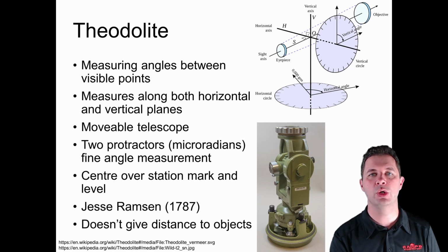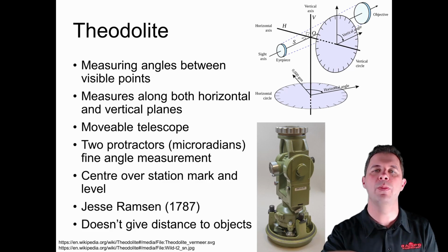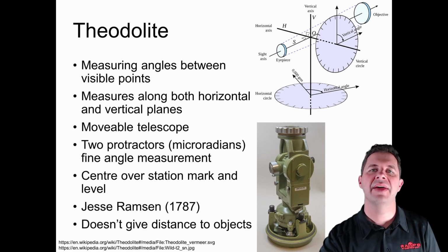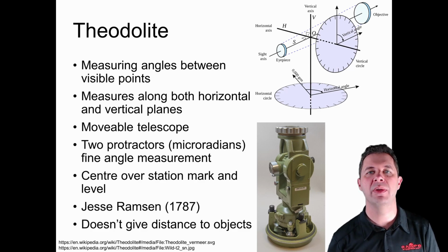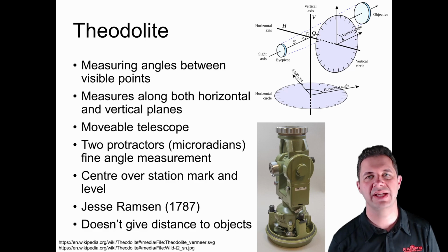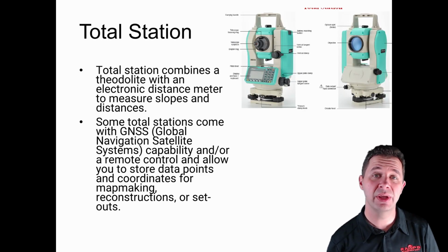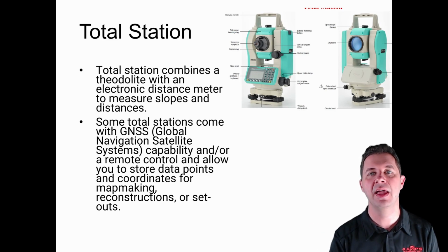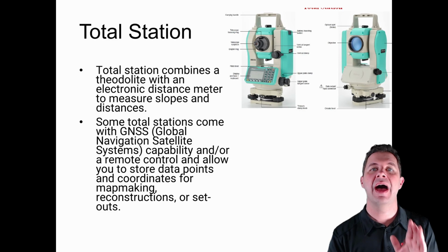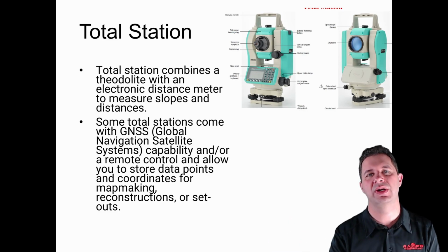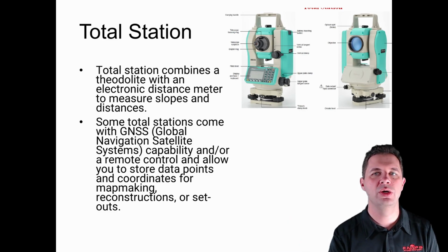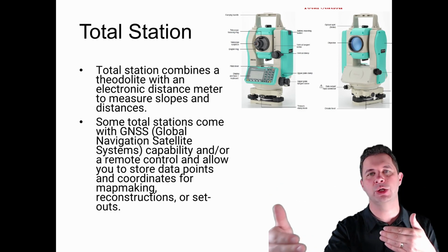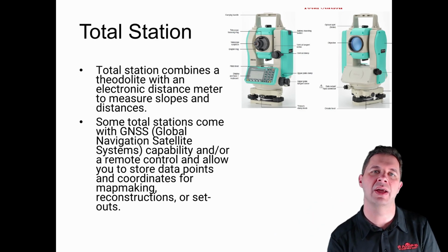And so what we'd need to do is measure that somehow using maybe some rope or a tape measure or some sort of a laser rangefinder or something like that. Now, theodolites used to be quite common, but these days we typically use a total station. And a total station does similar things to a theodolite, but with a whole lot of electronic smarts in it, like built-in GPSs. It also has a distance measuring system that allows us to measure using EDM the distance between our total station and the thing that we were measuring, a control point or something like that.